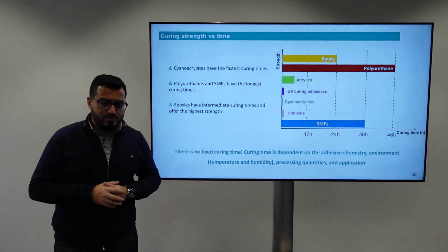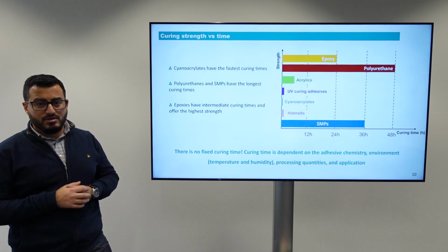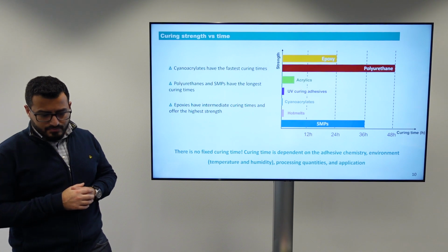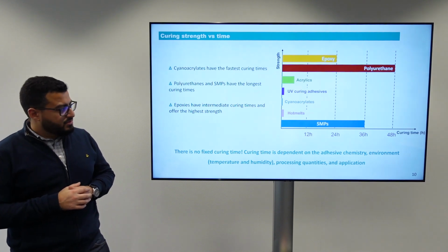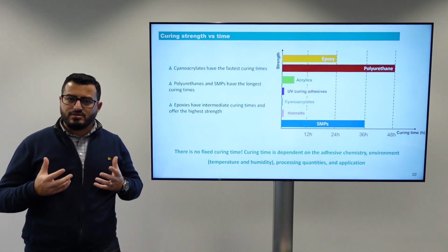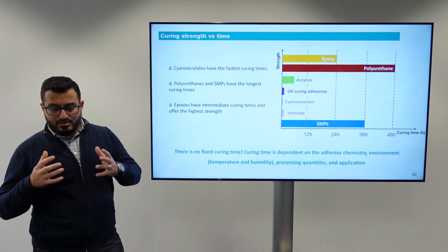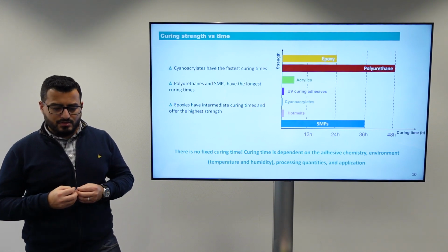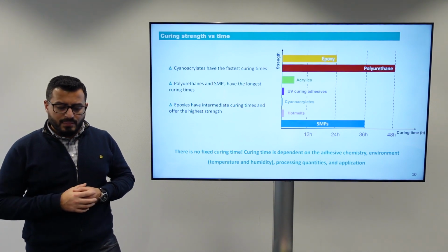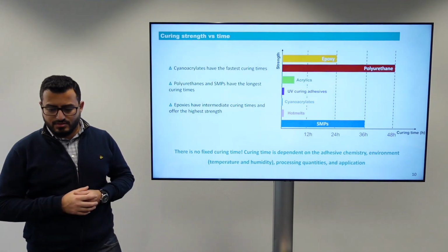Epoxies in that sense have an intermediate curing time, but of course it can achieve the highest strength. So in that sense, what is important to note is that there is no fixed curing time for these adhesives. The curing time is actually dependent on the adhesive chemistry, also the environment, the temperature and the humidity of your application, the processing quantities, and also the type of the application itself.